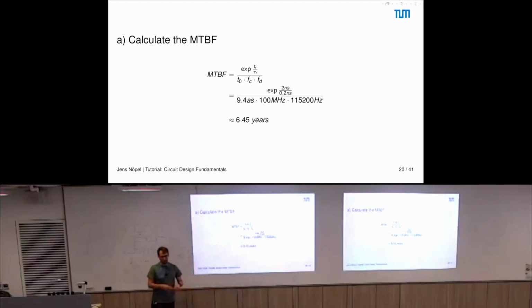The baud rate of UART corresponds to the frequency with which the UART is running. Yeah, the baud rate is the frequency, and it is the frequency we want to sample. This is then this one here, right? So this is our baud rate. And Fc is the sampling clock, which the device is running on. And these are the 100 megahertz. So maybe a little bit of explanation for this UART.